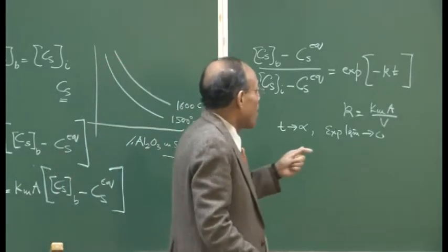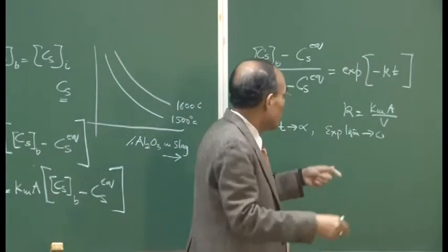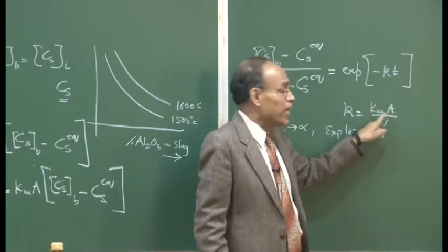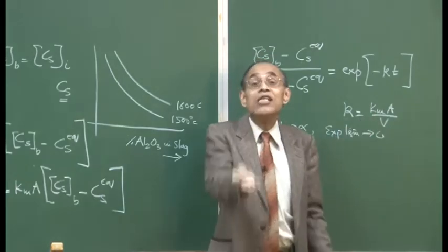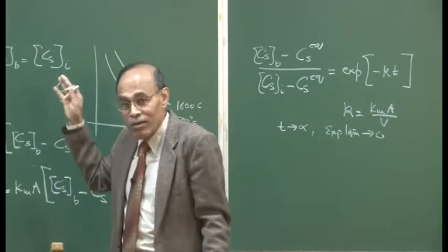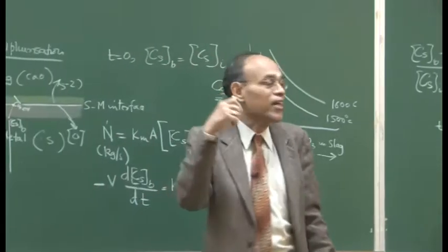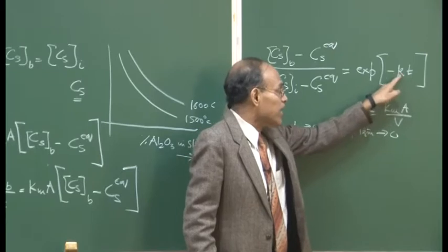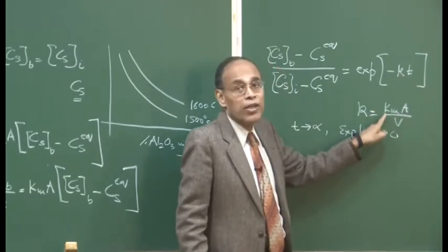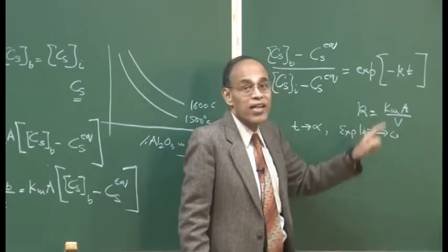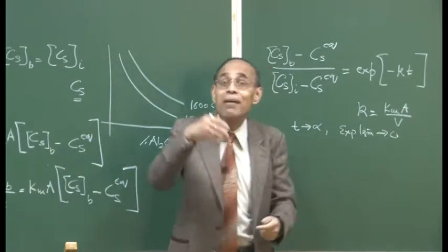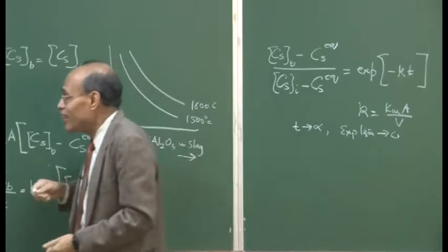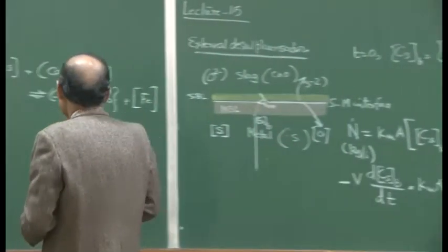So, that is not a process parameter, that is an operating condition, and that is a fixed condition. But these are processing parameters: the interfacial concentration A and the mass transfer coefficient. These we can increase or decrease by carrying out the process under certain conditions. So, for a large rate constant, it is imperative that we require a very large mass transfer coefficient and very large A, and that is embedded in the desulphurization process, which I will discuss when I describe the technique of desulphurization. In the desulphurization process, what happens?